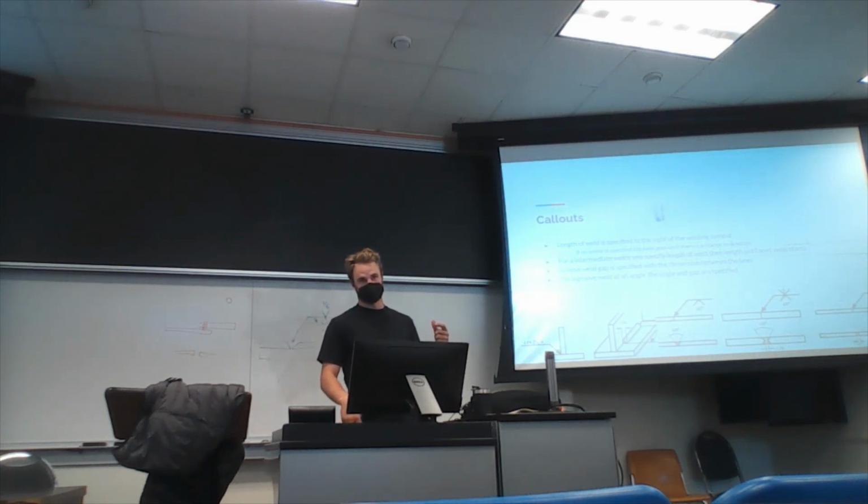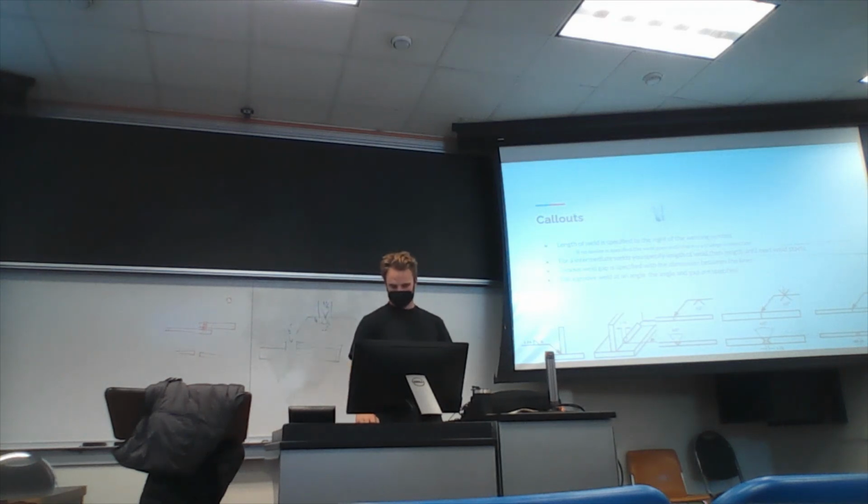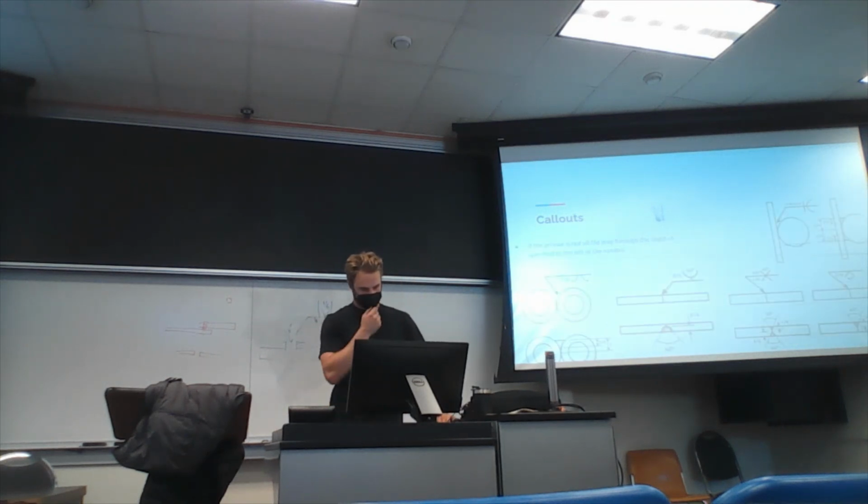Is that good? Same thing if it's just a butt joint. You would just change that to parallel lines, and this wouldn't be beveled, it would just be straight walls with an 1/8 inch gap. Yeah, I think I just talked about that.